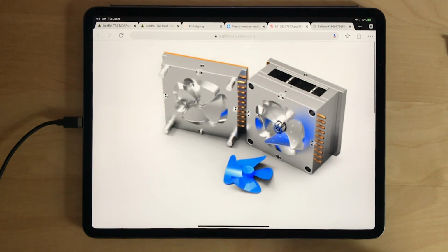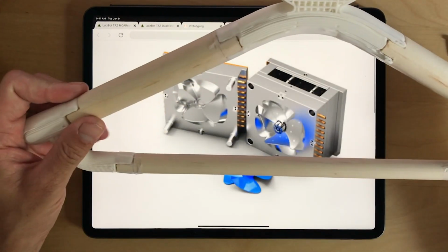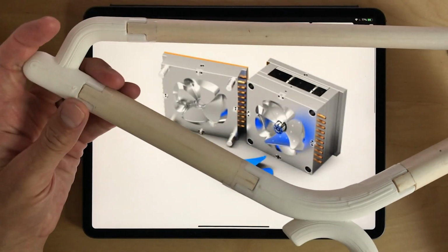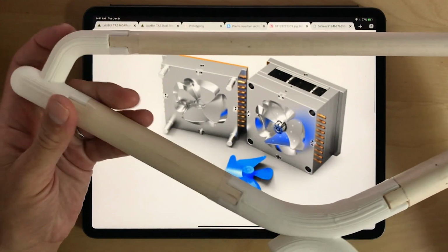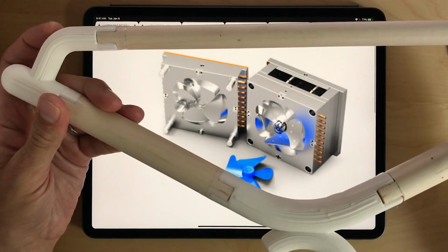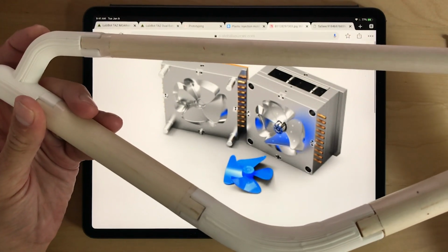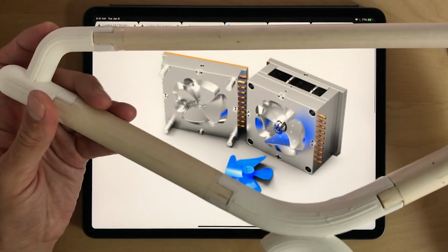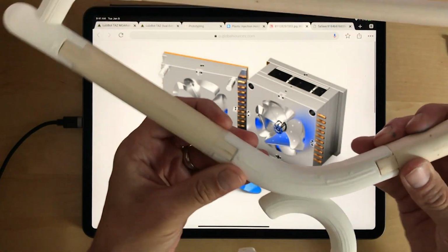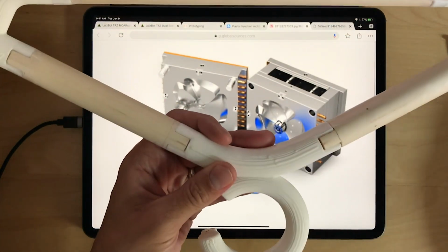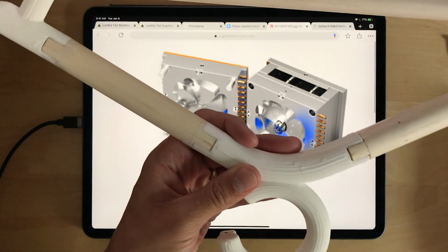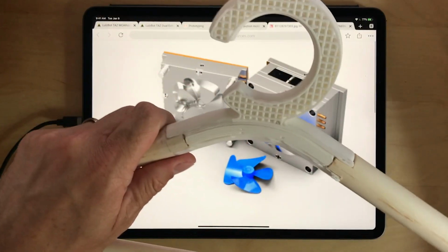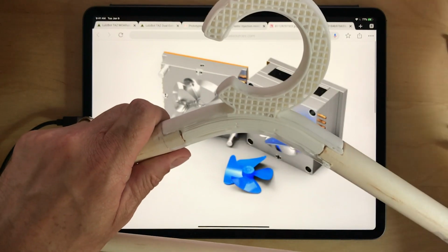One person also asked about strength calculation or testing. So this is again something you do with your in-house testing. You can 3D print these also solid. I printed those not solid to just save time and material. But this is more the first visual study test. Then I could 3D print this solid, then the prints will be harder, and then really try to get very close to the actual final result.